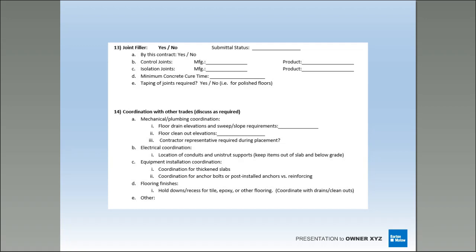Coordination with other trades. Most pre-pours, I'll have the plumber, the electrician, everyone else in there, at least one from their group, and I want that commitment from them that the floor drains are going to be set at the designated elevations we all decide on. The cleanouts, prime example. I've been to projects before where all the cleanouts were set to finish floor. The flat work guy goes in there and they're tight as ever. They're not low, they're not high, they're perfect.